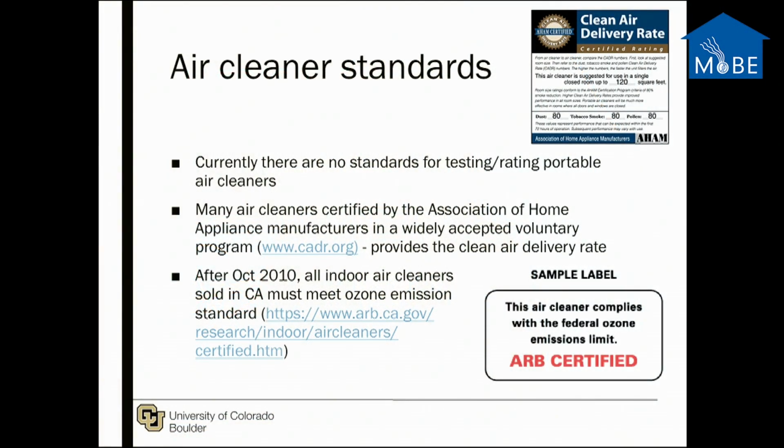Currently there are no standards for air cleaners, so I get questions all the time about which air cleaner I should buy, and it's actually very confusing to the consumer. There is a voluntary certification program that you can look at to see whether your air cleaner is going to work in your home. This is the Association of Home Appliance Manufacturers certification, and it will give you the clean air delivery rate. This label up here, for example, shows you that this air cleaner will clean 120 square feet. Well, that's not a lot of space, so if you have a 500 square foot space you're trying to clean, you need to buy 5 of these, for example.